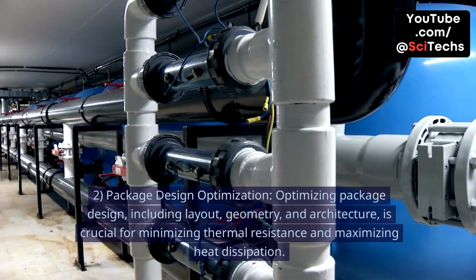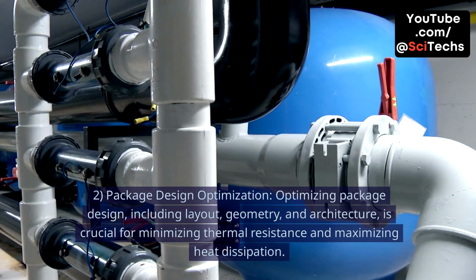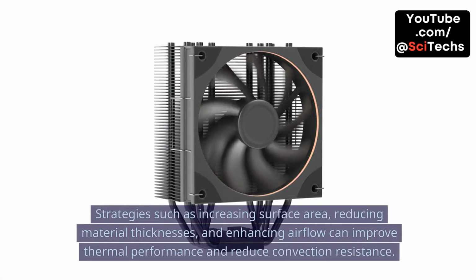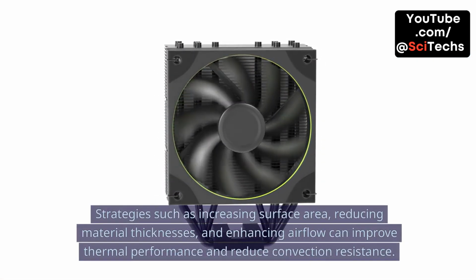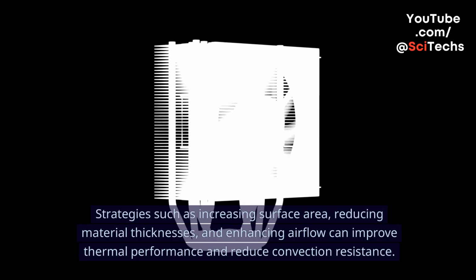2. Package design optimization. Optimizing package design, including layout, geometry, and architecture, is crucial for minimizing thermal resistance and maximizing heat dissipation. Strategies such as increasing surface area, reducing material thicknesses, and enhancing airflow can improve thermal performance and reduce convection resistance.